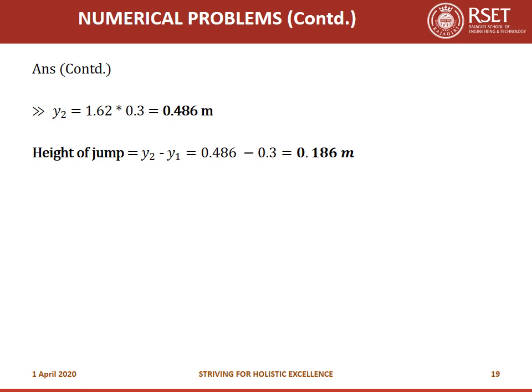They have also asked for the length of the jump. Now I've not defined any expression for length of the jump in the theory that I've discussed before. It's a very short expression: length of the jump is 6 times the height of the jump. This I have not explicitly given beforehand in the slides. This is for you to understand. Please keep it in mind.